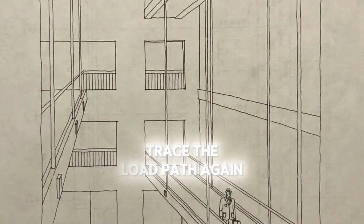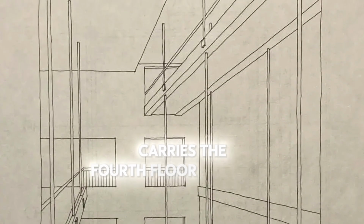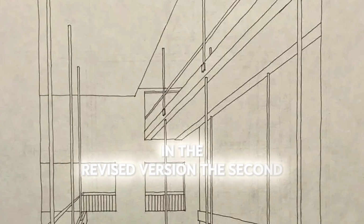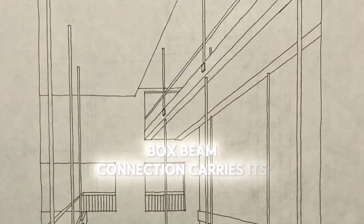Trace the load path again. In the original, the fourth floor connection carries the fourth floor walkway, and that's it. The second floor's load goes past it, into the rod, up to the roof. In the revised version, the second floor walkway now hangs from the fourth floor walkway. So the fourth floor box beam connection carries its own walkway, plus the entire walkway below it, plus everyone standing on both. The load on that connection doubled.